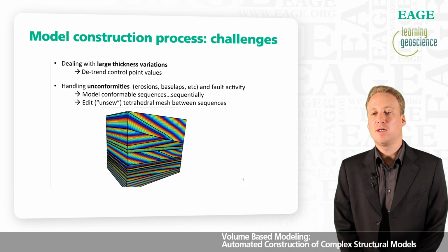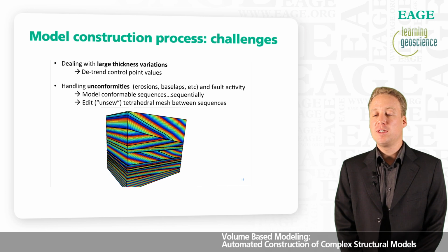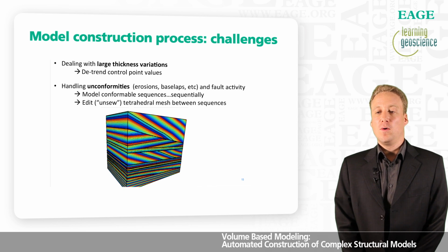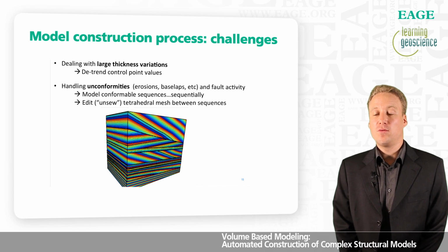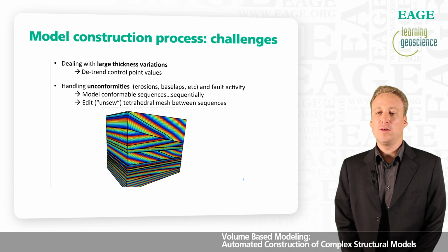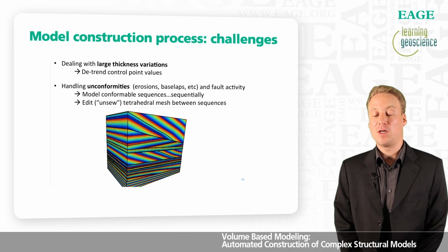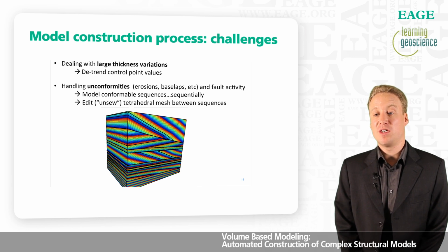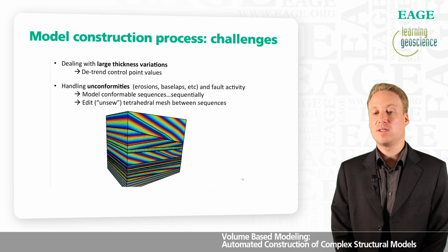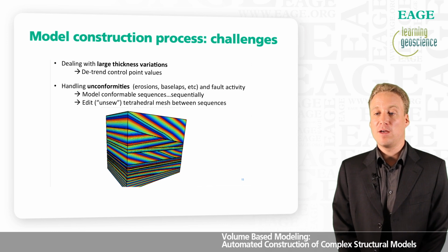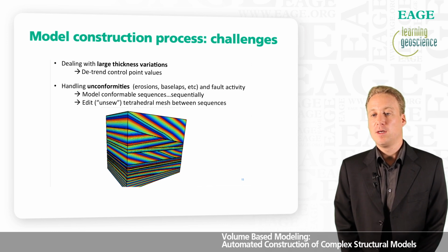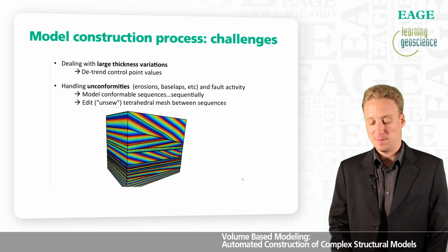Because we are using a constraint for smoothing the interpolation that will minimize the variation of depth and thicknesses, we can get artifacts when trying to interpolate this stratigraphy function on models that contain large depth variations, for example, in the data. You can see that it's the case on the images shown here on the left, where we have some artifacts in the interpolation because of the thickness variations.